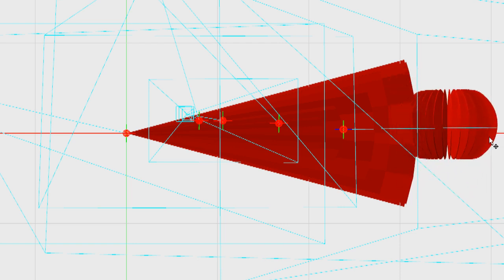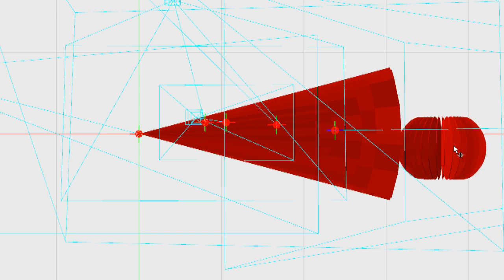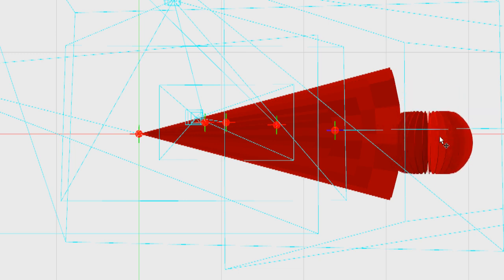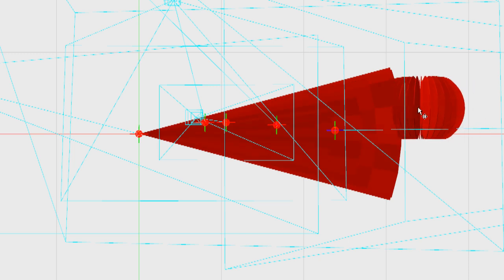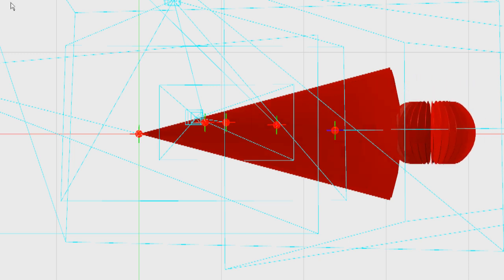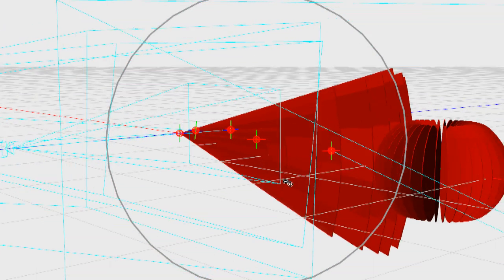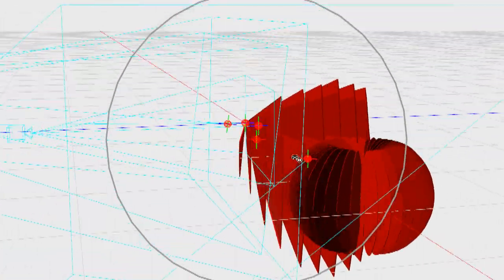Now, this is the main reason why the antenna trackers have become so popular. Because what it allows you to do is to use these high gain antennas that have got a very narrow beam and sensitivity pattern. But obviously the benefit of the antenna tracker, what is it? It will always keep it pointed at your plane. So you can get great long range, not have to worry about making sure it's pointed exactly in the right position. So we still have the same problem though, remember. We've still got the problem of the linearity of it, yeah? It's either vertically or horizontally polarized.